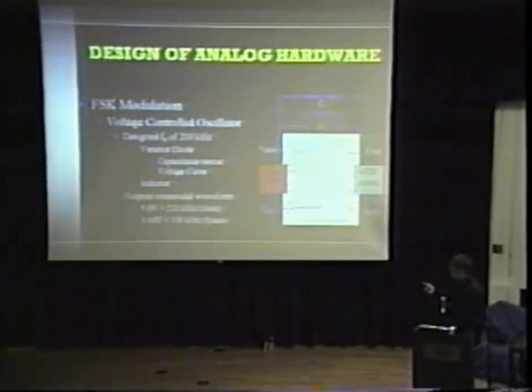The system is designed for a center frequency of 200 kilohertz, and the varactor diode is basically acting as a capacitor. In reverse bias, a varactor diode has capacitor properties. Using a capacitance versus voltage curve in the data sheet, I could determine a nominal capacitance and determine the required inductor.